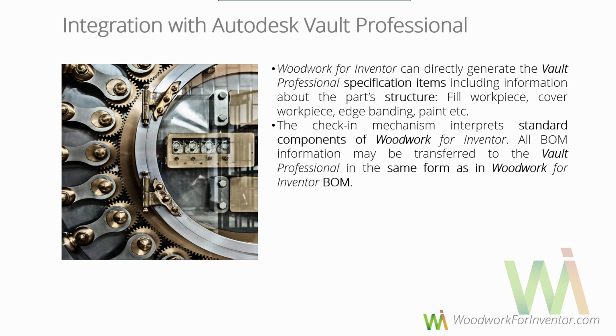As you understand, those should be shown as assemblies in the specification. Therefore, we have our own method of describing standard components so that they will be shown in the specification as if they were designed as assemblies, without needing to make them assemblies in fact. And all this information can be passed to the vault in the same way as it's shown in the Woodwork for Inventor bill of material.